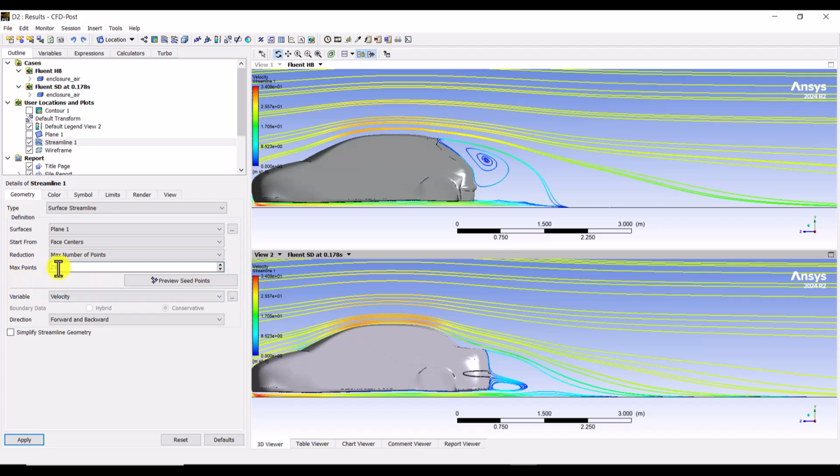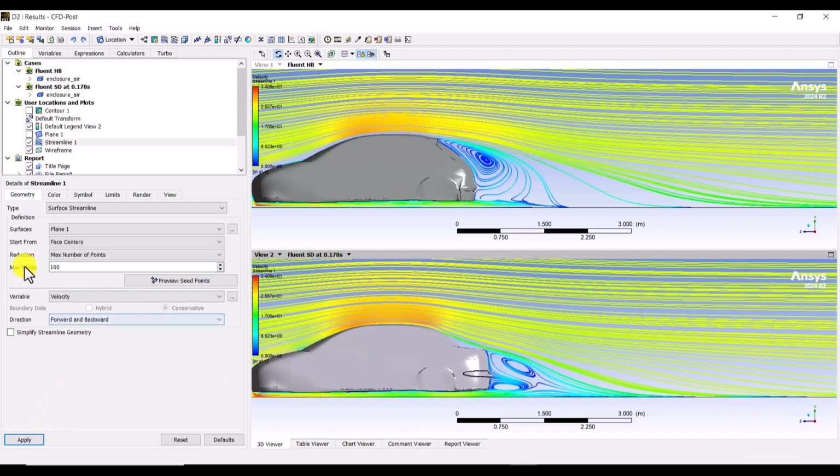By increasing the number of that, we can have more streamlines, but notice it will increase our computational costs. But here it is. You can see the streamlines right now. What we've said about the wake regions, the separation point, and the vortices formed behind the cars are depicted. You can see a big vortex on the rear of the hatchback model, while with the Sedan model, we've got vortices just behind the car after the trunk, with two small wake regions.